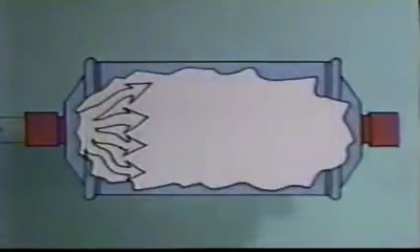All filter dryers introduce some pressure drop, even when they are brand new. A check of their construction will let us see why pressure drop goes up as they go about their job. Quality filter dryers are built so that all flow first must pass through the main filtering element, a highly compacted filter media with fiberglass as a base. The filter material must be tightly controlled in manufacturing so that it is loose enough to allow as much flow as possible, but still tight enough to do its filtering job. Filtering that may mean removing contaminants that are smaller than the eye can see.